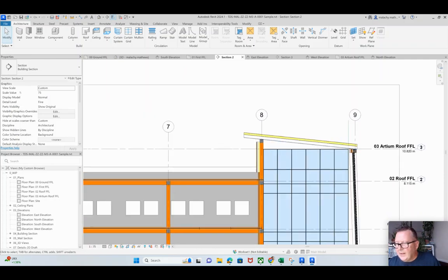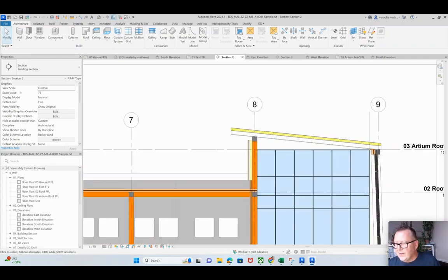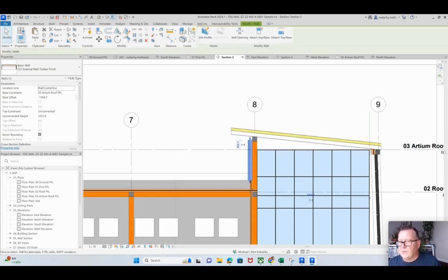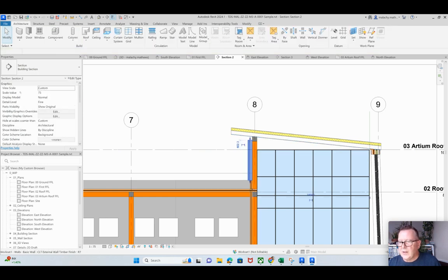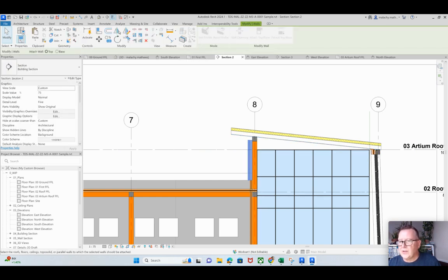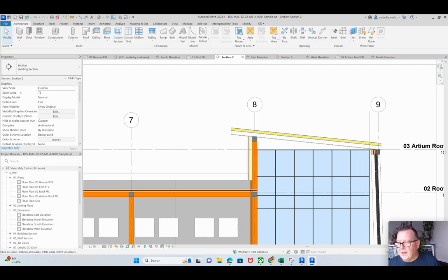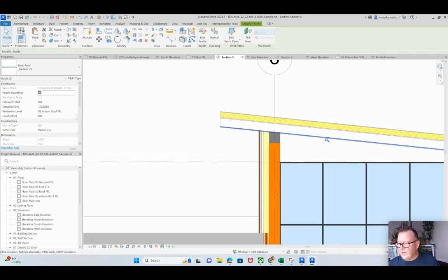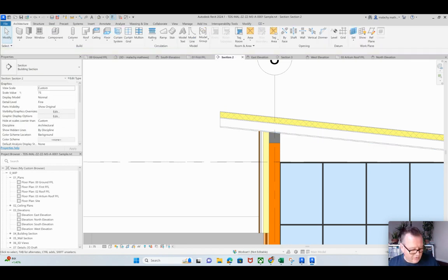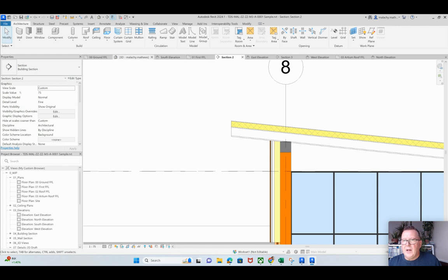And yeah, so that's kind of that's it. That is a solid wall in there. That's plasterboard that you're seeing, and that one should probably go to the underside of this one here. So I can pick it and I can go touch, chop, and base to that one. Now I did a little bit of a sneaky in there in that I created a roof within the architectural plan so that I could use that particular tool.